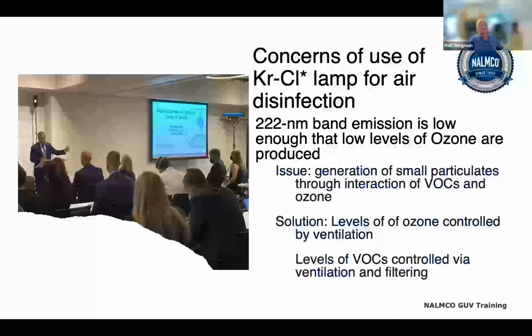The solution is obviously that we need ventilation to control the levels of ozone, so it is not recommended that the 222 be used in situations where there is no or very little ventilation. Furthermore, that controls not only the ozone, but also the volatile organic compounds. And if the air going into the room is filtered, that further removes the volatile organic compounds.